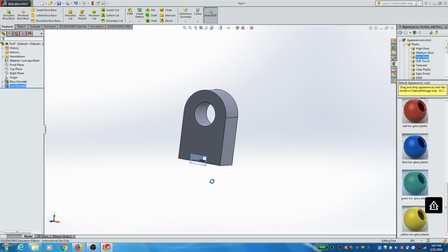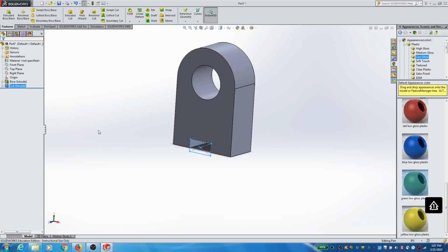I'd like to show you how to do this by going back and editing your original sketch. Okay, so this cut-through feature is the same type of operation as this hole, right? It goes all the way through the part. Therefore, I could have included this on the original sketch and then done one extrude operation. So what I'm going to do here, guys, is I first want to show you, you can delete these functions. So if I want to go back, I don't have to do Control-Z, Control-Z, Control-Z back.